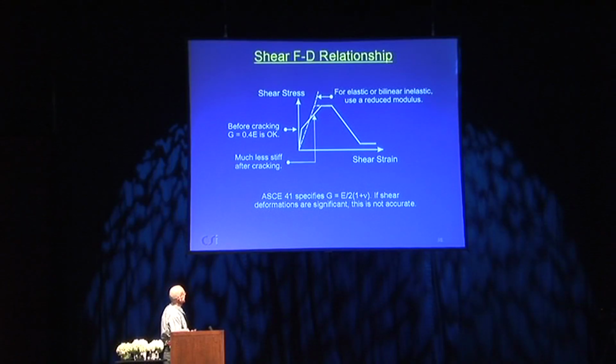I didn't do a very good job there. The important thing here is that a shear stress based on simple formula is not very accurate. This is a little more detail here. Before cracking, it's actually okay to assume G is 0.4 E. After that, it's much less.